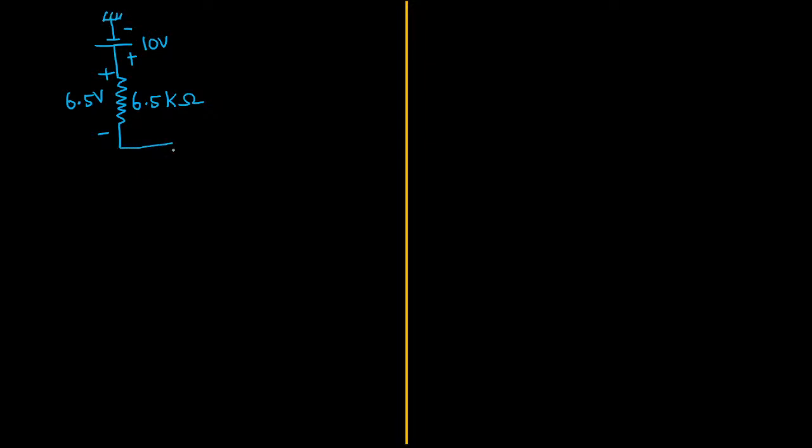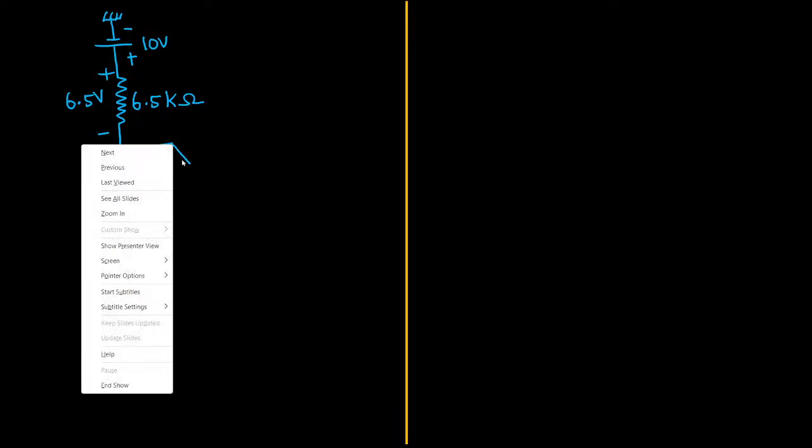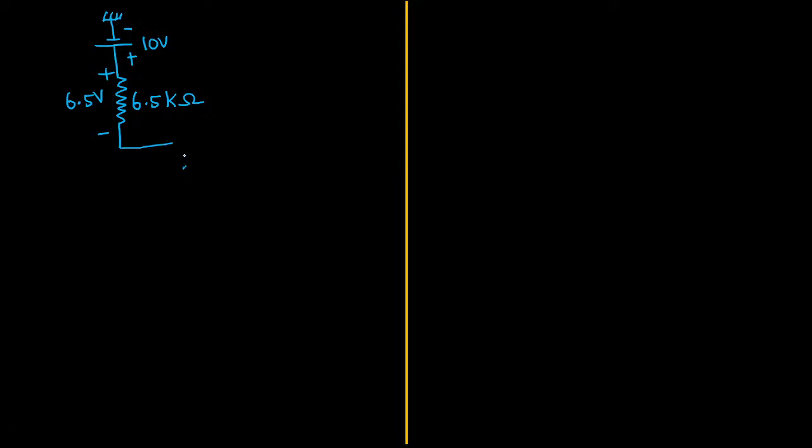After that I am traveling through the first transistor, and we know this transistor can be replaced through the base. I can cross the transistor from base to emitter. Sir, our transistor is in active region. Why am I not crossing collector to base? We are always going from base to emitter. Why are you not thinking about the collector? When the transistor is in active region, the collector junction is in reverse bias. Yes or no? Only the emitter junction is in forward bias. Don't forget that. So you can't consider that junction. You should travel only in this way. They have given that this is 0.65 volts.